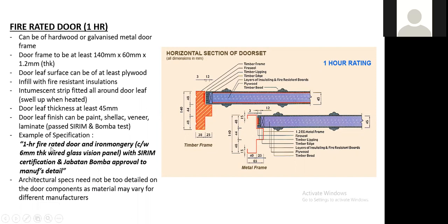Okay, you just need to say only 1 hour fire rated door and ironmongery. Okay, with ironmongery as well. So some come with 6 mm thick wired glass vision panel, with SIRIM certification and Jabatan BOMBA approval to manufacturer's detail. Okay, this is good enough.